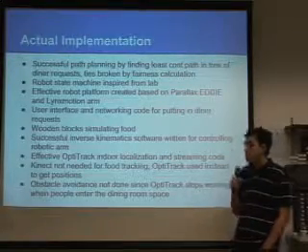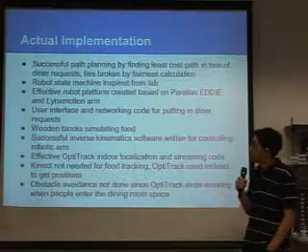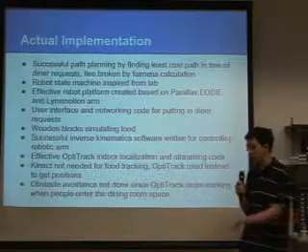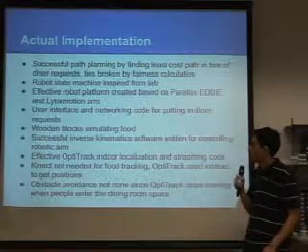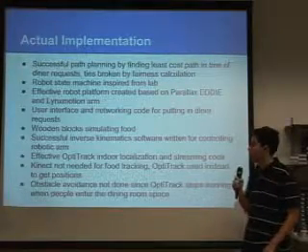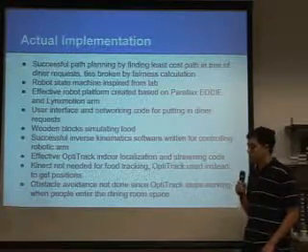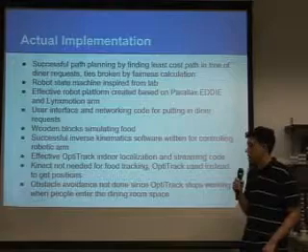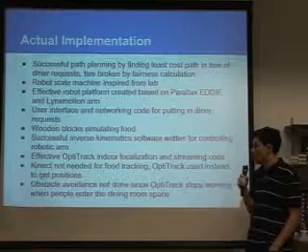And our robot is running a state machine that's inspired by the work we did in the labs before. Our robot platform is based on the Parallax Eddy, and we have a Lynxmotion arm. We have networking code and a GUI for putting in diner requests and the chef's table. And we have effective inverse kinematics code. We also are using OptiTrack for indoor localization, and we're streaming that to the laptop on the robot.